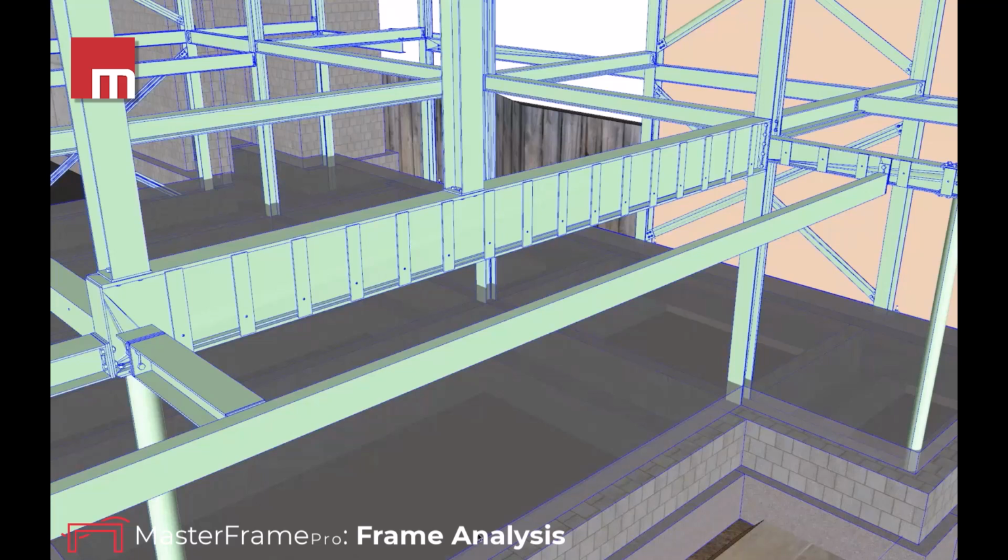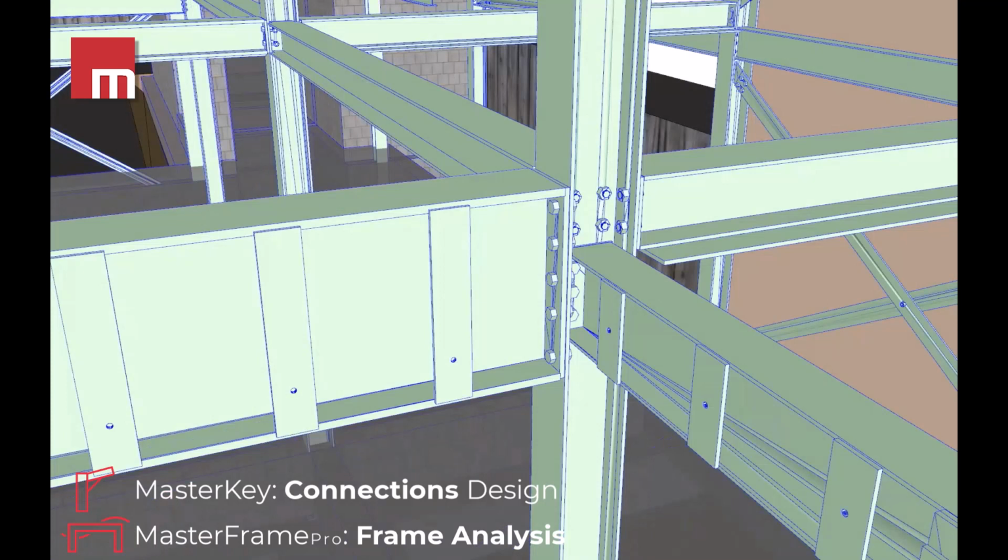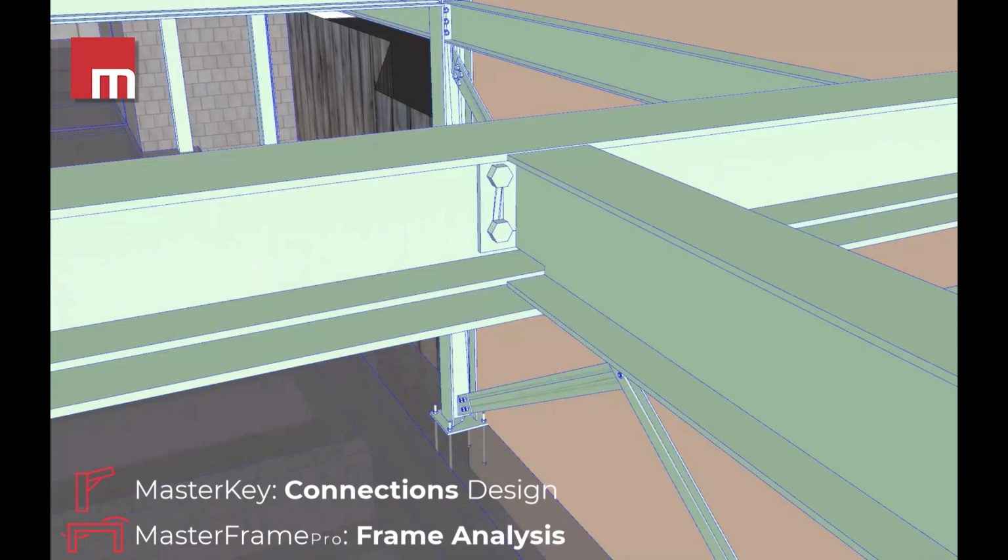So in this building, the fabricator carried out the design of the steel connections, but ADD used MasterSeries Steel Connections Designer for the preliminary design to ensure compatibility with their frame design for the different connection arrangements, such as the four-way beam to column flexible end plate simple connection you're looking at the minute. We've got a beam to beam flexible end plate simple connection, plus we can also specify flange toe plates here if required as part of the latest version of MasterSeries.